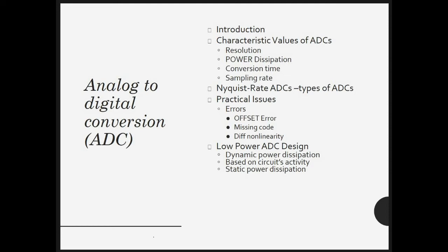An ADC may also provide an isolated measurement, such as an electronic device that converts an input analog voltage or current to a digital number proportional to the magnitude of the voltage or the current. However, some non-electronic or only partially electronic devices, such as rotary encoders, can also be considered ADCs. The digital outputs may use different coding schemes. Typically, the digital output will be a 2's complement binary number that is proportional to the input, but there are other possibilities as well. An encoder, for example, might output a gray code. The inverse operation is performed by a digital to analog converter, which gives the analog value at the output.